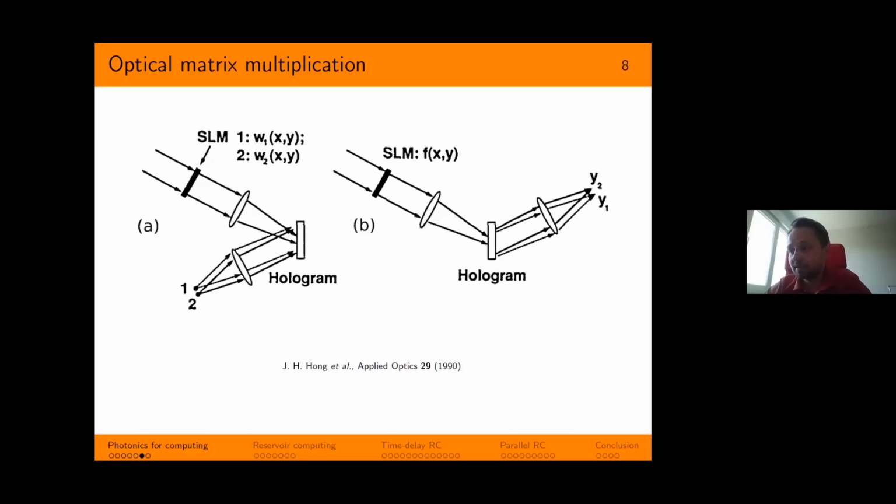Unfortunately, despite the elegance of the first implementations of optical perceptrons, they still have some drawbacks, namely their inefficiency. And this is again the inefficiency of interactions in photonics. Holographic coupling is fundamentally limited by the diffraction efficiency, which often lies below 10%. And furthermore, our experiments are based on free space optics, which are bulky experiments, and it's not apparent how this holographic concept can be translated or integrated in photonics on chip.